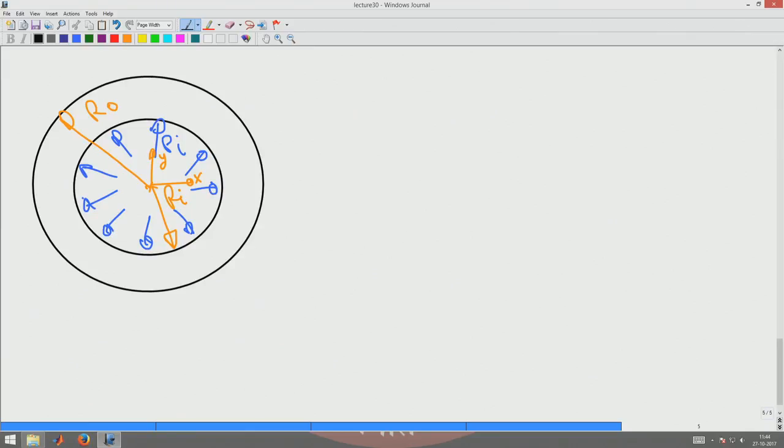This is the outward normal to that surface, and the pressure is acting opposite to the outward normal. So, that is a negative stress. And this normal is nothing but negative of e_r, where e_r is the radial basis for this cylindrical polar coordinate system.